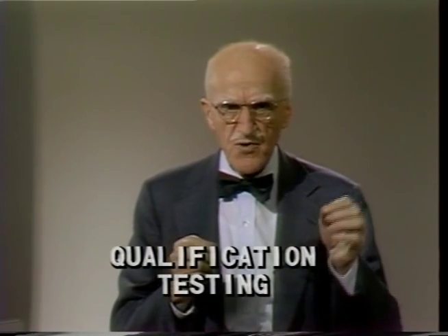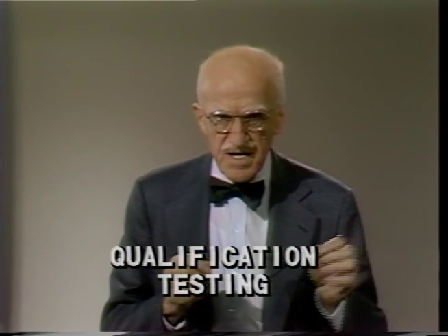Now, as to quality assurance of the vendor's design. The usual early warning is qualification testing. The vendor submits samples to be tested in the laboratories by trained technologists. This provides useful early warning despite some limitations. Mainly, the sample should represent future production, and the design will not be changed without the buyer's agreement.